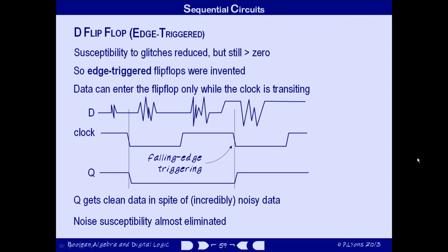We won't spend time looking at the details of the edge triggered flip-flop mechanism. They aren't more complex than the other circuits. You just put a couple of crossed over feedback paths around a standard flip-flop and you'll find that analysis similar to the one we conducted earlier for the RS flip-flop will reveal the edge triggered behavior. We're only omitting this analysis because it takes a while and because it's so similar to something we've already covered, and it doesn't add a great deal to our understanding of what's going on. Instead, we'll move on to one more type of flip-flop, and this one's the last, I promise you.